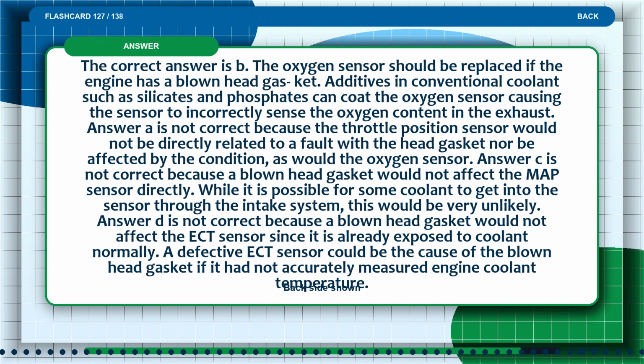The correct answer is B. The oxygen sensor should be replaced if the engine has a blown head gasket. Additives in conventional coolant such as silicates and phosphates can coat the oxygen sensor, causing the sensor to incorrectly sense the oxygen content in the exhaust.